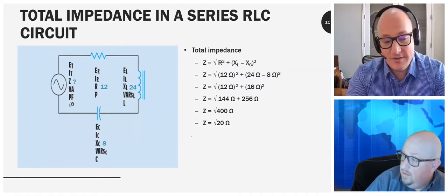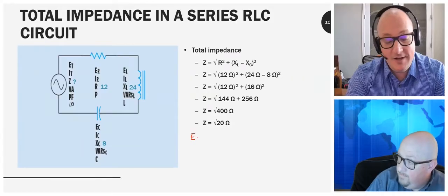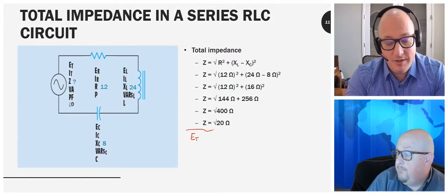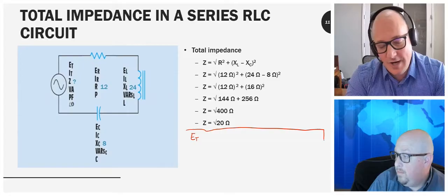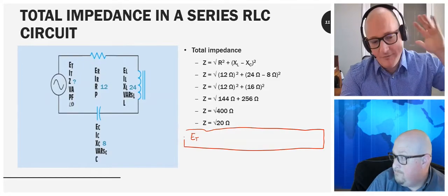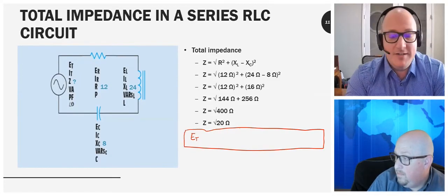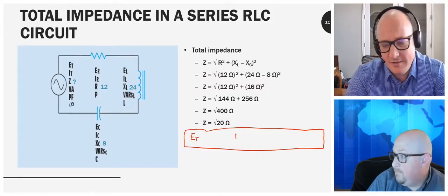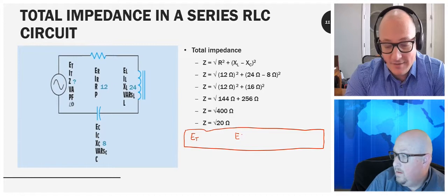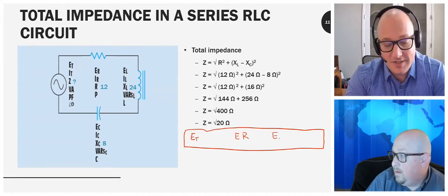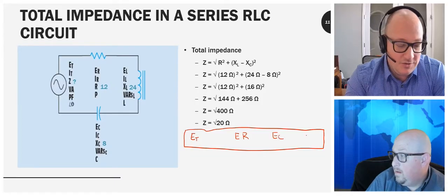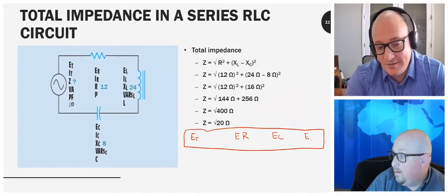Right, so like the slide you have, you'd have to take all those values in the cap and slide it just to the right of the inductor, right? So I'd have volts dropped across the capacitor, what's the current flow through the capacitor, what's the total reactance of the capacitor, what's the reactive power, or the VARs of C, and we usually just don't solve for the capacitance.